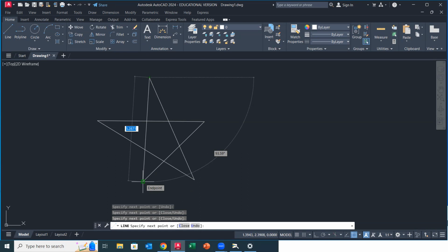And that means, if you click right now, when that green box appears, it's going to snap to that endpoint. So you can do it then. The other thing that you can do is, if I'm on a continuous line and I haven't started and stopped anywhere in between, this is just the same line command all the way through, I can hit C for close. So if I go C, enter, it closes it and it goes back to the endpoint.